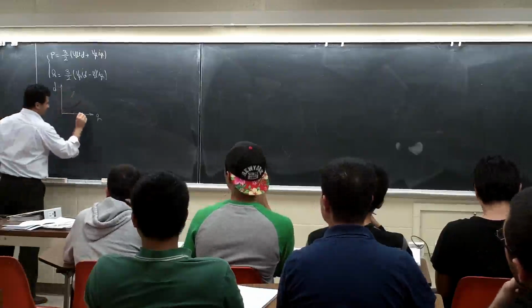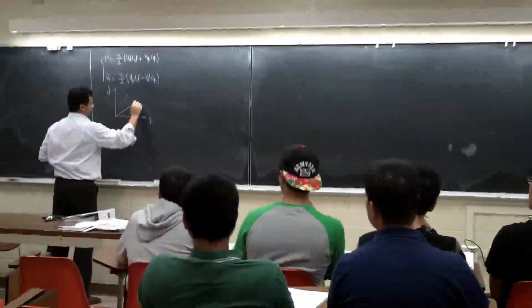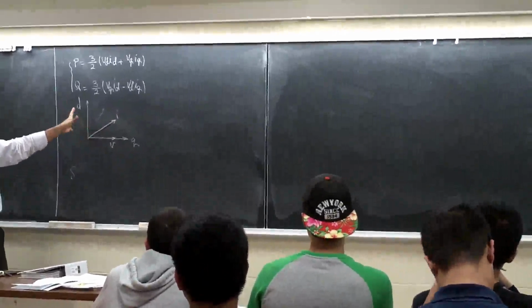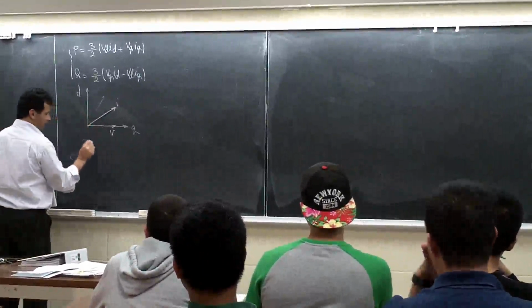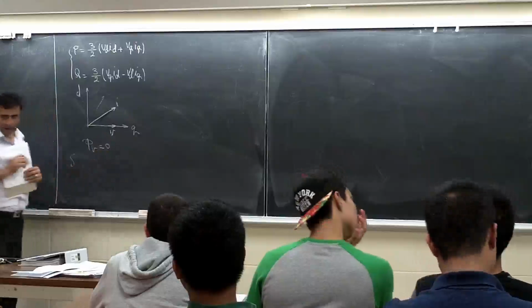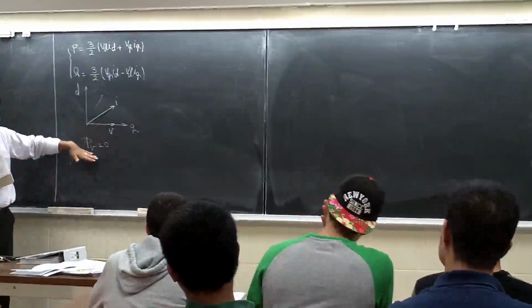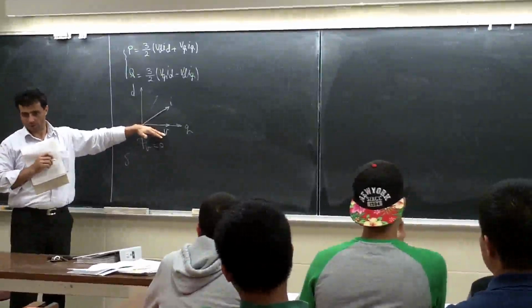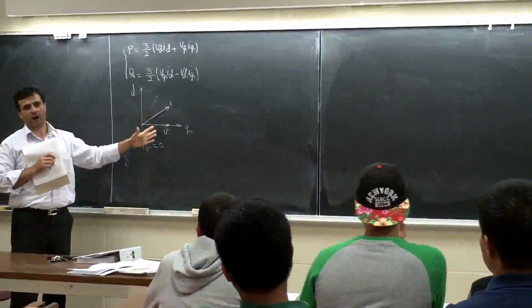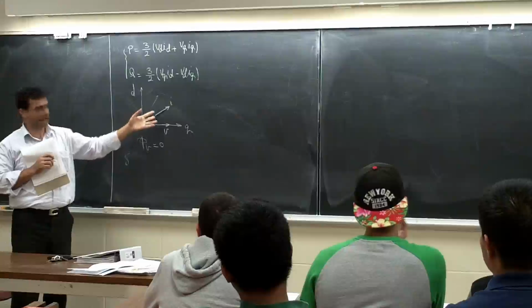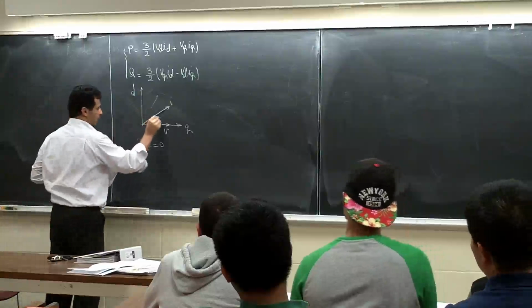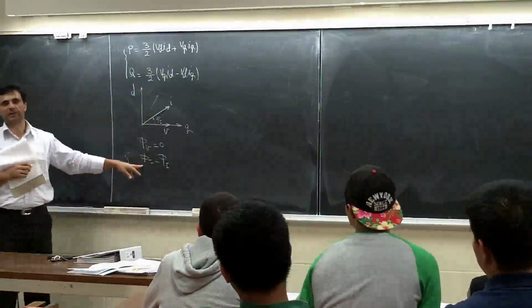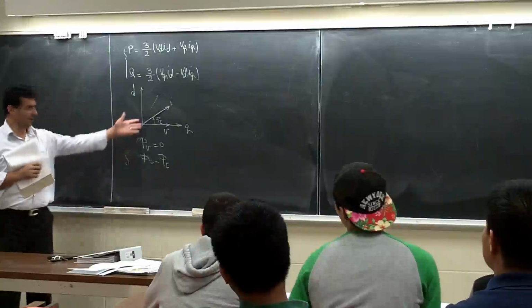If I select that, I have my voltage like this and, for example, my current like this, or this way, it doesn't matter. It's either leading or lagging, it doesn't matter. So basically here, phi V is equal to how much? 0, right? Because phi V was the phase between the V and the Q axis, if you remember, look at your notes. So this one is 0, only we have phi I, and phi is phi V minus phi I, right? So this is a leading case.